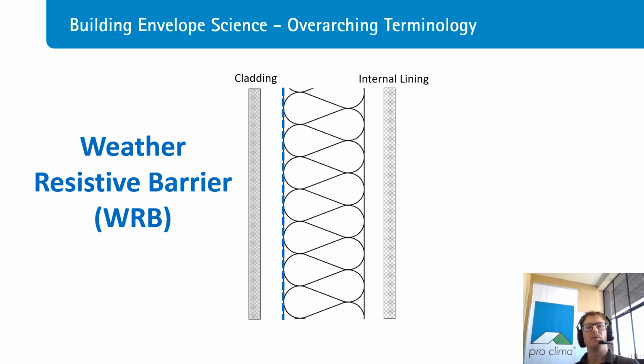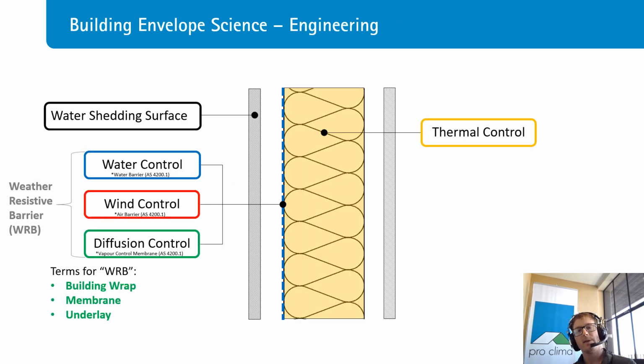And the fundamental philosophy here, or the fundamental question that we're trying to answer is, can you do a weather resistive barrier on the outside of the structure as the airtight layer? Can we achieve passive house just with that exterior weather resistive barrier? So when we include insulation to that system, we know that in winter the outside of that structure is going to get colder.